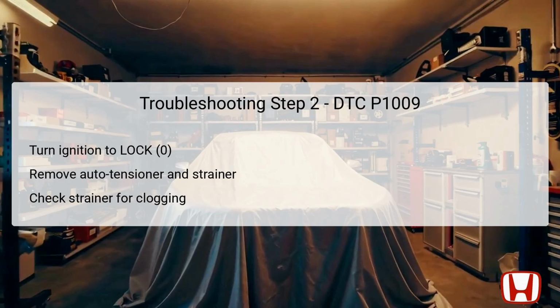For the second step in troubleshooting DTC P1009, first, turn the ignition switch to the lock position, which is also referred to as position 0, essentially powering down the vehicle's electrical systems. Next, carefully remove the auto tensioner, which is responsible for maintaining tension in the timing chain, allowing access to the VTC strainer.